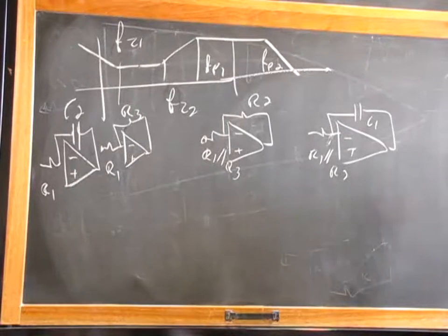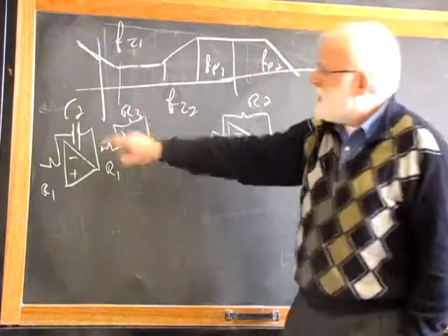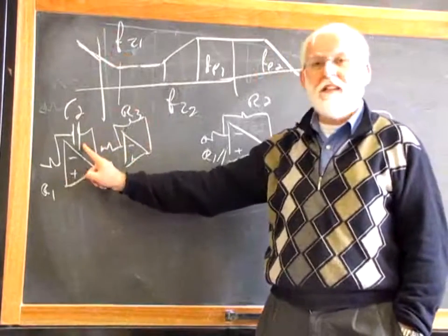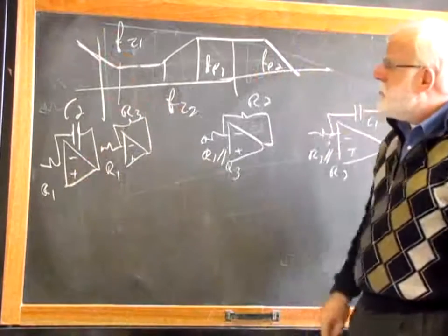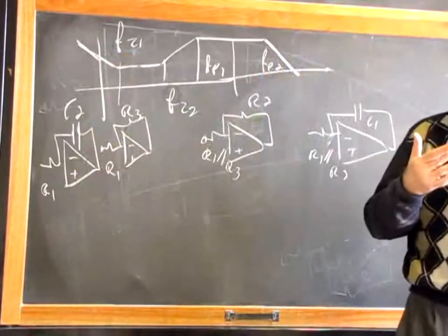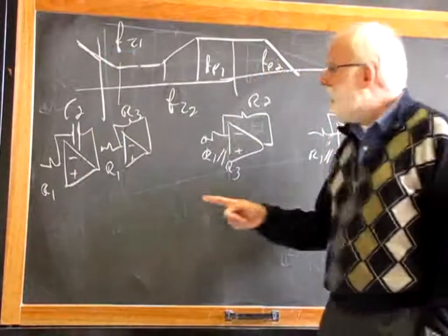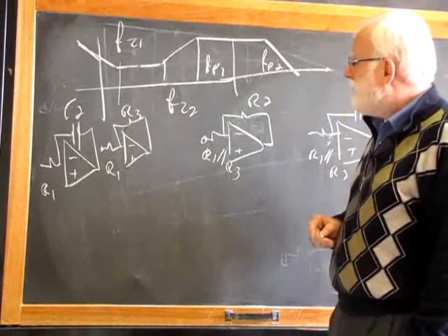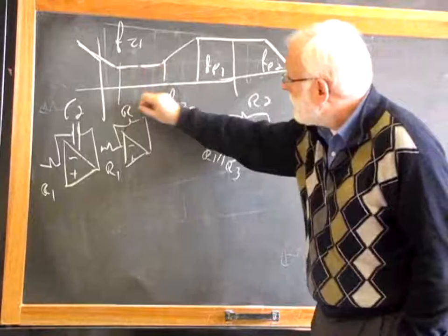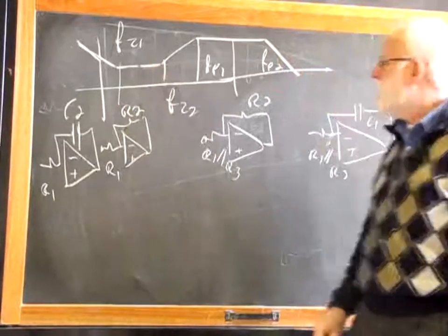This is more or less the evolution working on my transfer function. In the first part, there is only C2 and the feedback path that makes the integrator. Then C2 is a short circuit with respect to R2, not an absolute short circuit, a short circuit with respect to R2. Then we have this constant gain. R2 and R1 is the gain, negative R2 over R1.